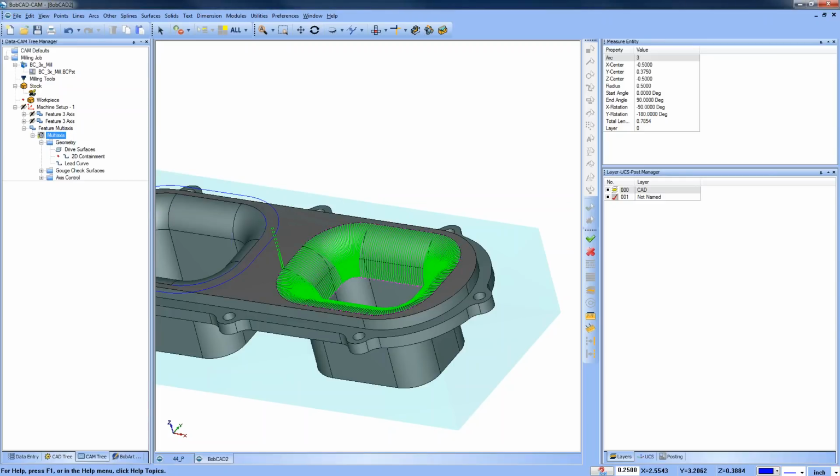Why wouldn't you just use a corner rounder? Well, it might be a mold-based application where it's an irregular radius size. You may not have a cutting tool. It may be a one-off part, so it doesn't really make sense to buy the tooling. You want to use the tooling that you have. So those are some considerations that you have.